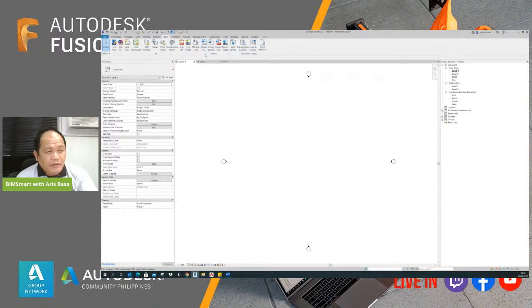The negative thing about importing a CAD file is you are importing all these lines. Sometimes it messes up the project, and sometimes some of the lines are left behind. And when you start doing the printing, may mga natitirang lines. Usually don't use import CAD. I recommend linking CAD. So let's go to linking a CAD file.